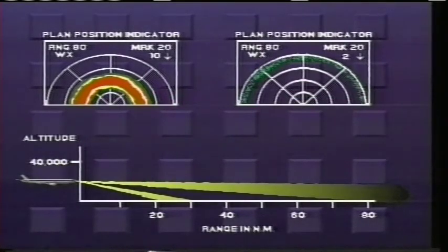Around 20,000 feet, switch to the 80 nautical mile display range and set the antenna tilt control to 10 degrees down. Slowly rotate the antenna tilt control up while watching for weather cells, until ground is being only lightly painted on the outer edge of the displayed range.